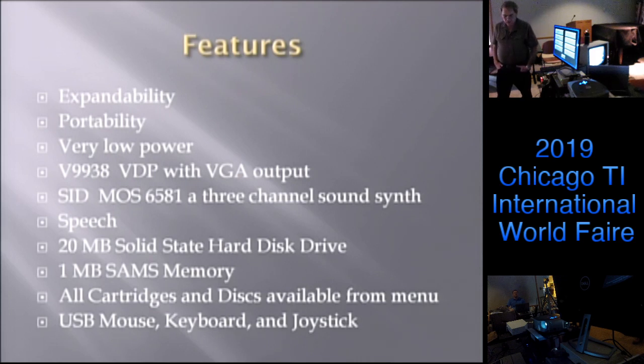So all the interfaces are USB. So you have a USB keyboard, mouse, and joystick that plug into it. They're micro USB connectors. And what I basically did is use a micro USB to a standard USB connector for the individual devices. There have been some requests to put standard USB connectors on the board, but that increases the real estate just a little bit. So, and the board is pretty tightly packed as it is, so I probably won't do that.